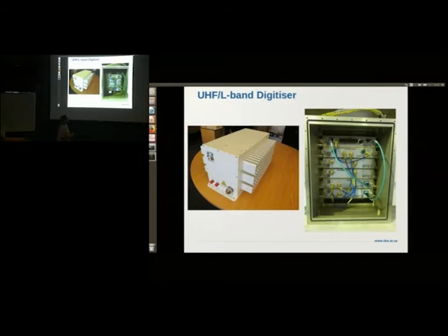Then we have two sampler units. Those are where the ADCs are actually located. And you can see the fiber units coming out here to what is called the D engine. This is the unit that packetizes the data, which takes the optics data and packetizes it into the SPEAD format. And then at this point, it's 10 gigabit per second Ethernet times 4 that goes into the antenna pedestal. And then from the antenna pedestal, it's a 40 gigabit Ethernet link that goes to the Karoo array processing building.